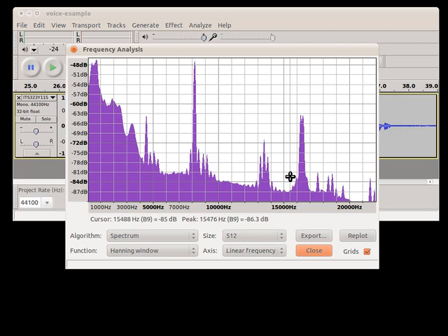So that's an example of our voice plotted in the frequency domain, and the previous one with the voice plotted in the time domain. So, coming back to our communication system, I talk, the microphone simply converts the acoustic signals, the sound waves, into electrical signals and sends those electrical signals as is, that is, looking like in these plots, to the wireless transmitter. So from the microphone to the wireless transmitter, analog signals.